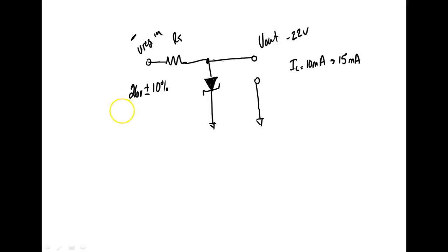Okay, so let's calculate Vin max, and let's calculate Vin minimum. So Vin max is going to be 26 volts. By the way, minus or plus, when you put these in the formulas, you want to use the absolute value of these. If you don't, you're going to get a minus R, and you don't have minus R. Plus 2.6 volts. And then my Vin minimum would be 26 volts minus 2.6 volts. So what we got for Vin max? 28.6. What do we get for Vin minimum?